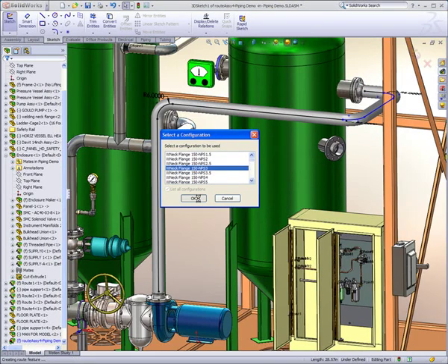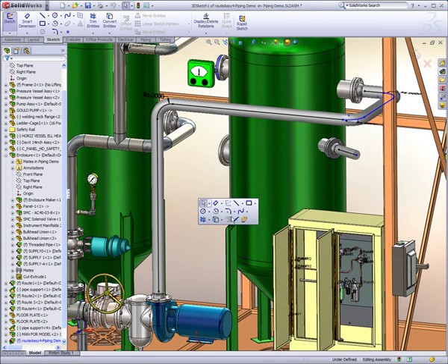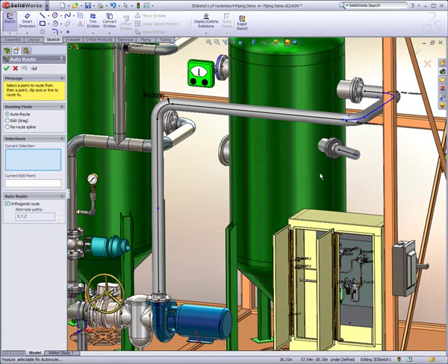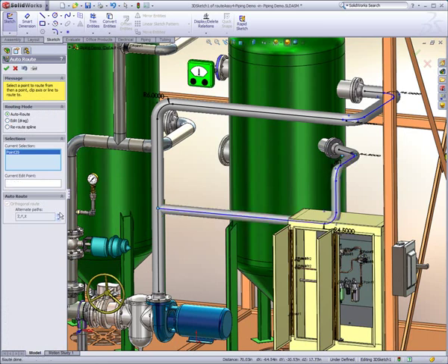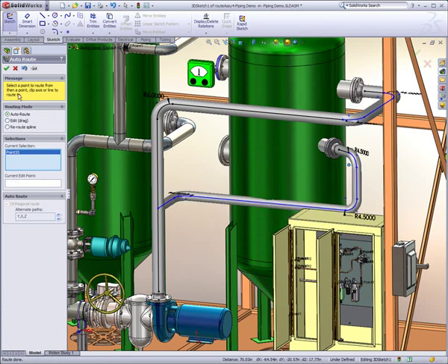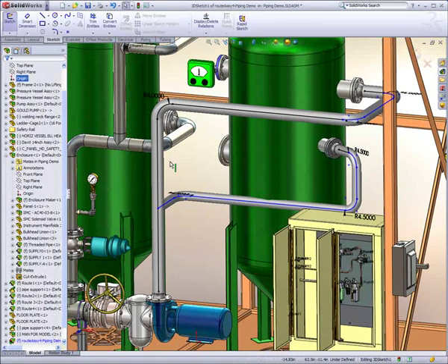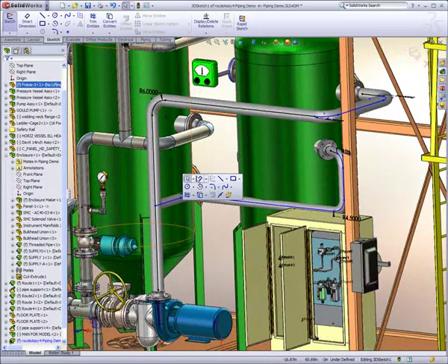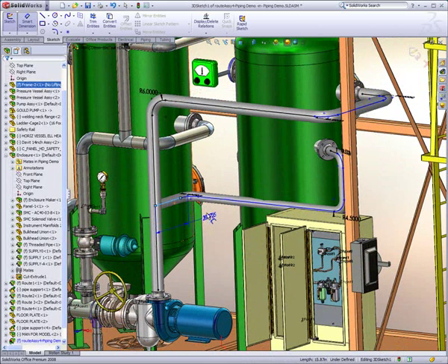Here, I'll connect a smaller flange to the piping spool. I can specify the intersection point by simply choosing a location in the existing pipe run. SolidWorks can automatically connect the two locations for me, and all I need to do is modify the size and maintain desired clearances. I can either drag the pipe into place or use dimensions to size it appropriately.